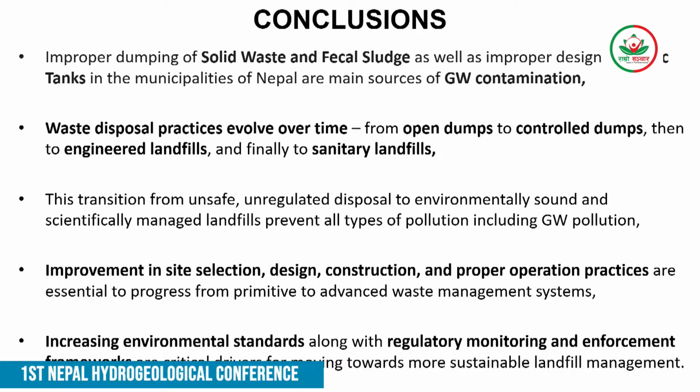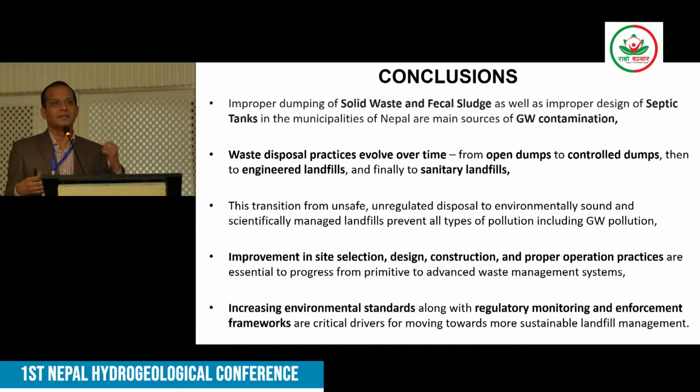I'm not going to go into detail about this. And finally, I want to say something here. The first thing is that we have to gradually change our open dumping practice. Almost 90% of our municipalities dump the waste. And we have to gradually convert these dump sites from controlled to engineered landfill, and ideally sanitary landfill. As an engineer, I would say engineered landfill at least.